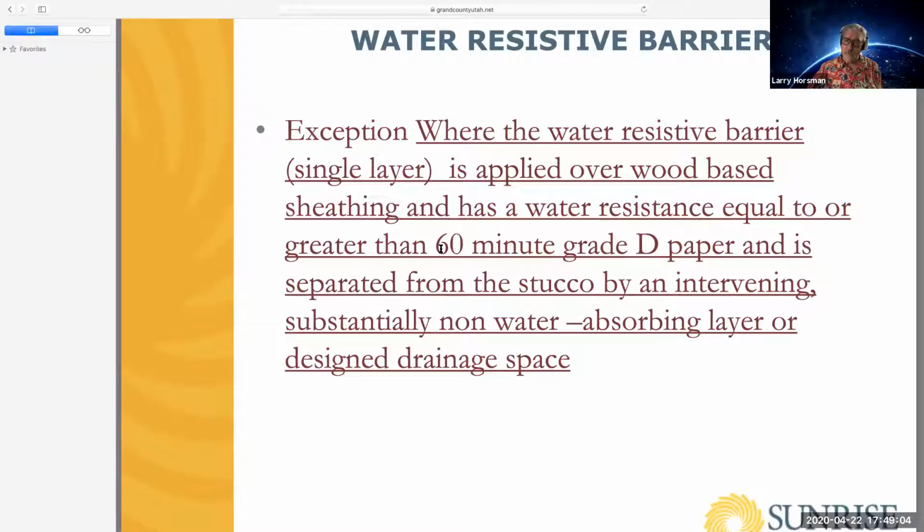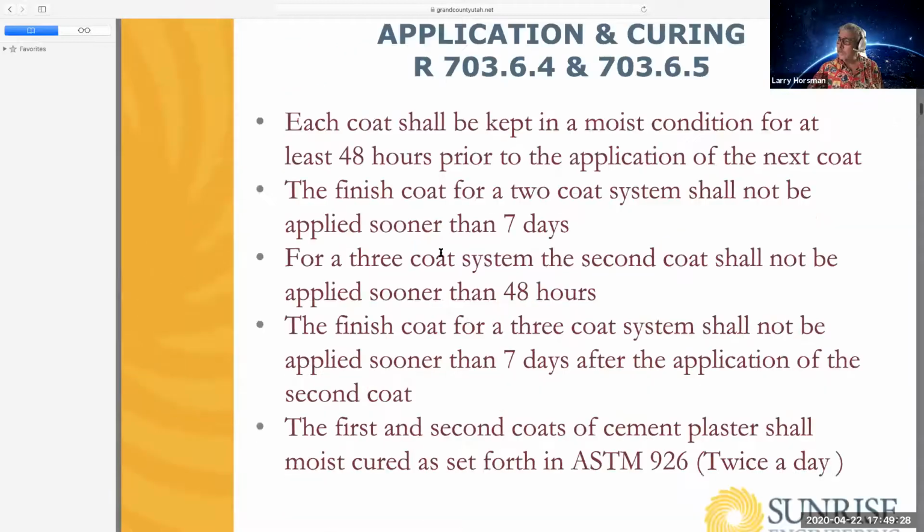That doesn't mean that's for a firewall. It's supposed to take about that long if you have water on the outside of the paper and it doesn't drain off, that it would take about that long for the moisture to penetrate that particular type of paper. And some of it is stamped with 60 minutes. And so I had somebody asking me about that.